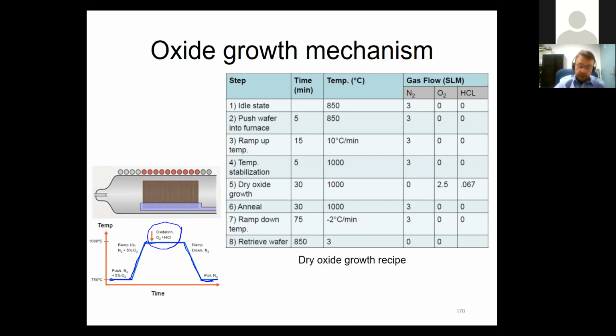If you do not wait for the cool down or the ramp up, first you can harm the tool because it can't catch up with the speed. Secondly, and maybe more importantly, you can build up a lot of thermal stress on your wafers. So all these wafers, once they are taken out from, let's say, 1,000 degrees to outside room temperature, 25 degrees, there's going to be too much of a sudden abrupt change in temperature, and it may build up an unequal amount of stress on certain points, and it may just break the whole wafer.